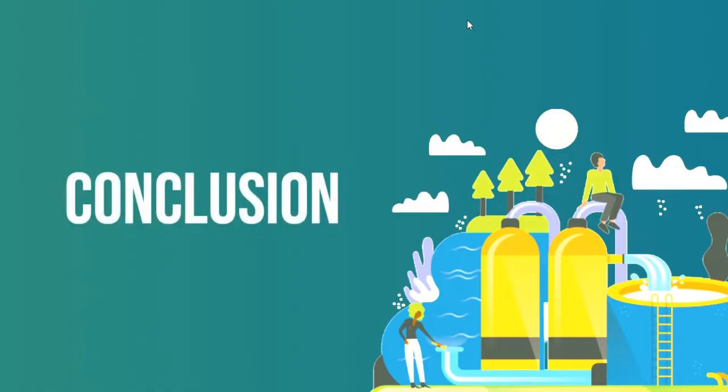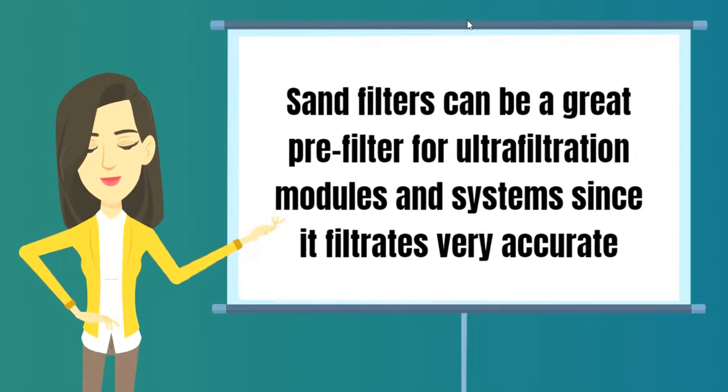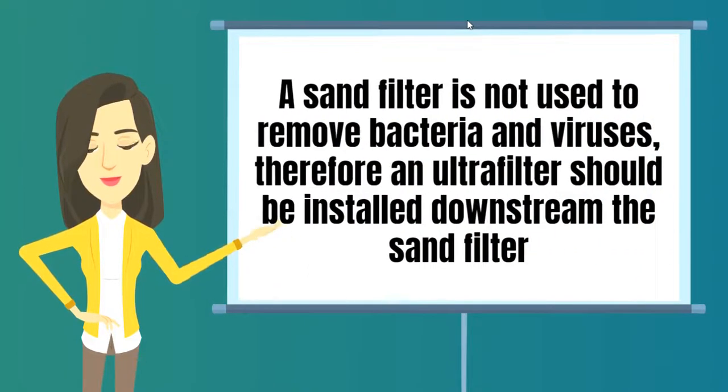In conclusion, sand filters can be a great pre-filter for ultrafiltration modules and systems since they filter very accurately. A sand filter is not used to remove bacteria and viruses. Therefore, an ultrafilter should be installed downstream of the sand filter.